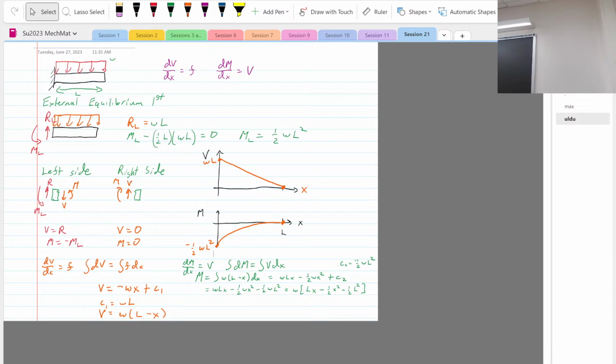Isn't it just P times? No, just what's the equation? Just what's the equation for bending stress? It's the flexure formula. Sorry, I'm drawing a blank. For some distance, My over I. Oh yeah, My over I, right? Okay, or negative My over I.